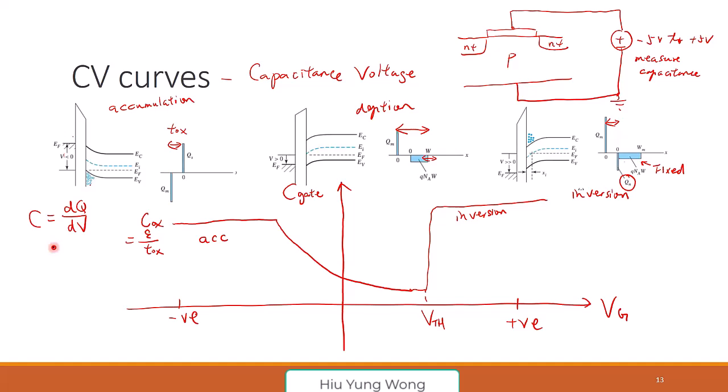You measure a capacitor just like a water pond, right? A reservoir. How do you know whether this is a big or small reservoir? You pour some water into it, Q, and you look at how the water level changes. Well, if the water level changes very fast, you think, wow, that's not a big capacitor for water, right? Because it may be very narrow. That's why you pour a little bit of water, then the level goes up. If you keep pouring water into the reservoir, the water level goes up, and assume there's no leakage. You will say, wow, this is really a big capacitor, correct?